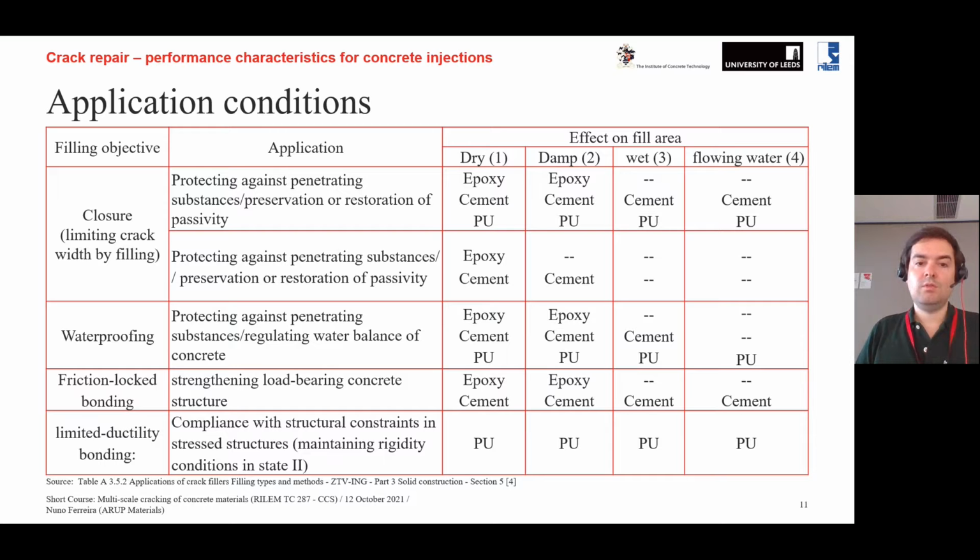Now, the epoxies, you really need to wait for a dry situation to inject the crack. But also epoxies, they can work from very low crack widths, 0.1, for example, 0.2, 0.3, 0.4. But again, if we have a thick section of crack or joint to repair, it's probably not recommended to use epoxies.